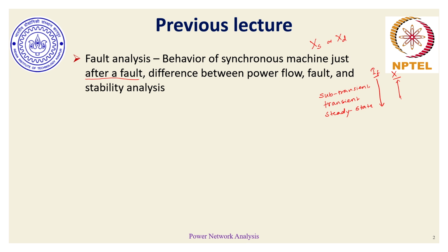And we also briefly talked about the difference or purpose behind doing fault analysis and the last module, which is stability analysis. Fault analysis is all about figuring out the worst case or worst possible fault currents during faults in a power network, and that's the reason why fault analysis is a subtransient period study, because only during the subtransient period will we be able to know what the maximum current is. In stability analysis, we are focused on whether the system, here being the power network, would remain stable following a fault or a disturbance.